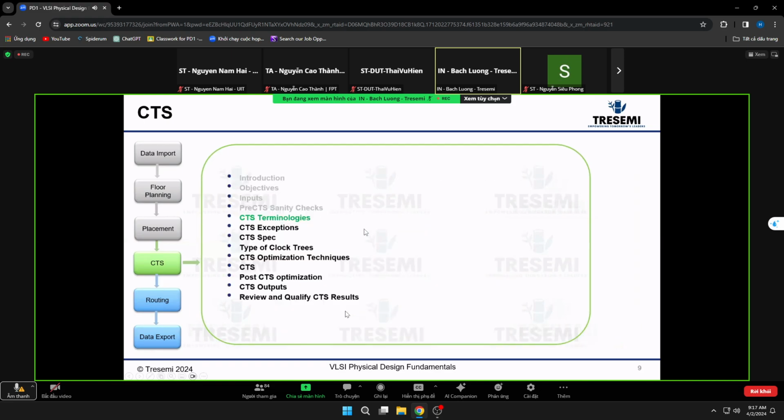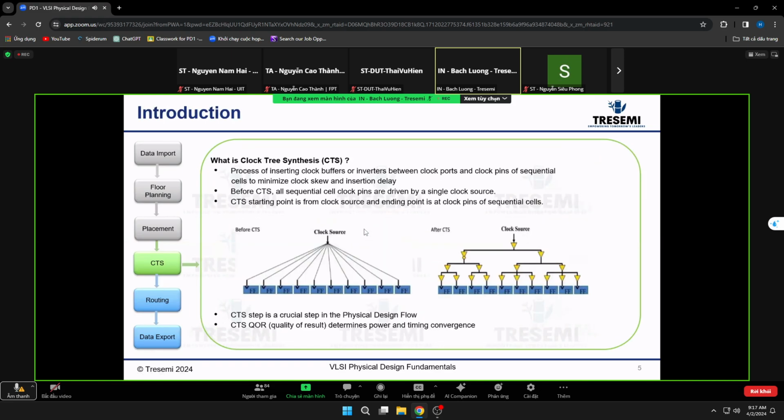If you go back to this picture from earlier, you can see we want to minimize the clock skew across all these flip-flops. We want the clocks to arrive at the same time, or at least within the clock skew target, say 30 picoseconds. So if this were a 900 picosecond insertion delay, we want it to be like 930 all across here if the target is 30 picoseconds.